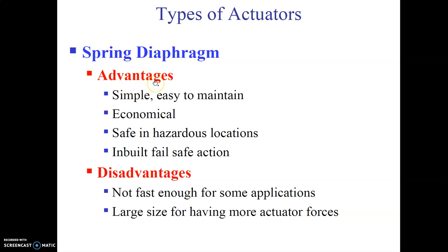Now if you see the advantages, in most of the control valves, this is the actuator that is used. Simple, because minimum number of components are required, and if you look at the parts, spring and diaphragm, they don't get damaged, so maintenance is less, it is cheap. Then being compressed air as the medium, it is safe in hazardous area. And due to the spring, it has got inbuilt fail-safe action. We need not have any extra in the actuator. By virtue of its construction, it provides this fail-safe action.